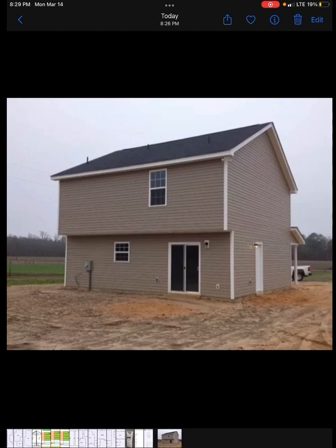So anyway, the bottom line is, when you're creating a layout for houses with a cantilever, when it's this small, at least for our purposes here at Archon with doing home scores, don't put that in the layout. Just make the first floor the same as the second floor in this situation, because otherwise you're going to have to add a new foundation with your home score paperwork, and it's just going to make everything complicated, and most likely you're going to get your home score rejected and have to redo it,